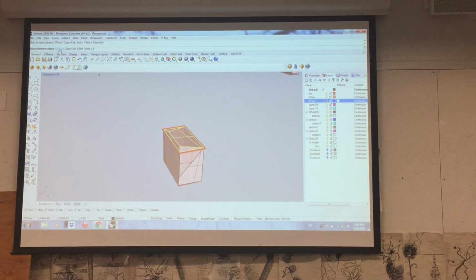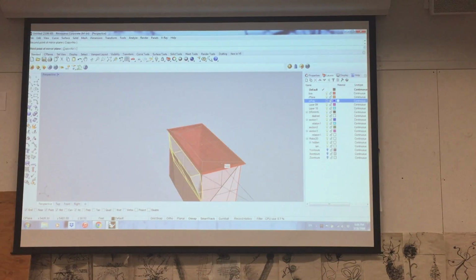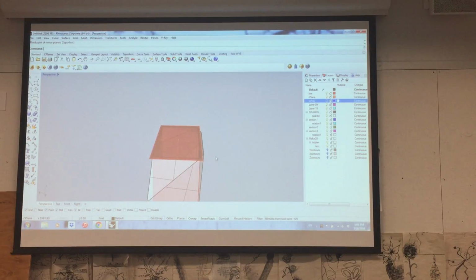So when I click that, I'm going to define 3 points of the plane that I would want this to mirror about. So you can think of that red splitting plane literally as a mirror. And we're going to define that with 3 points. I'll click here, I'll click here, and then I will click there. And now, let's say, get rid of that.